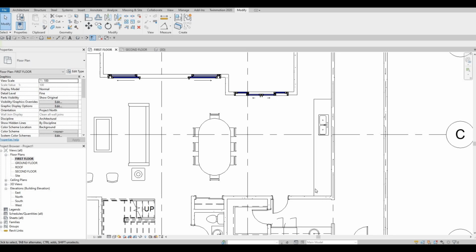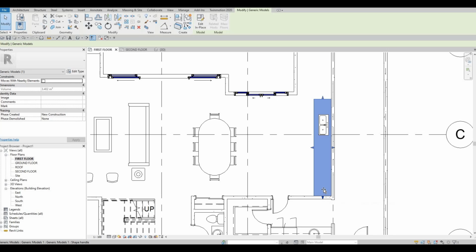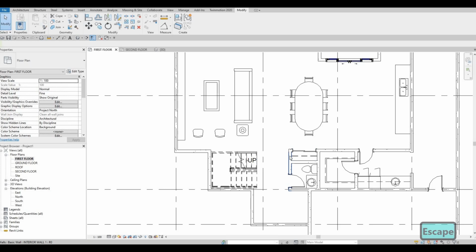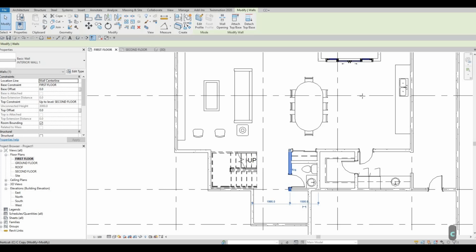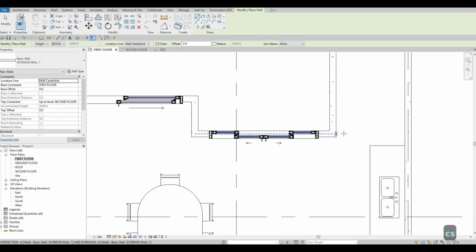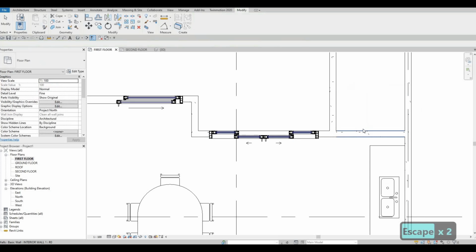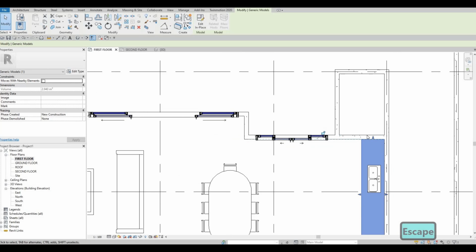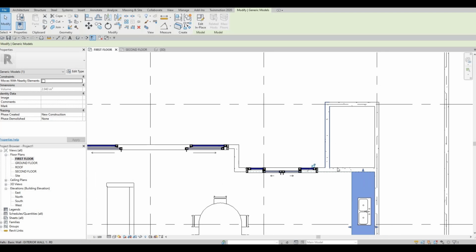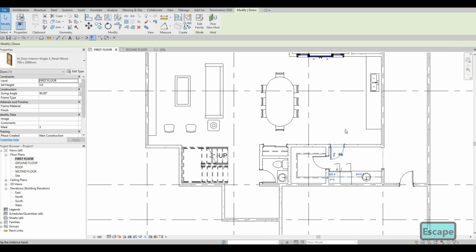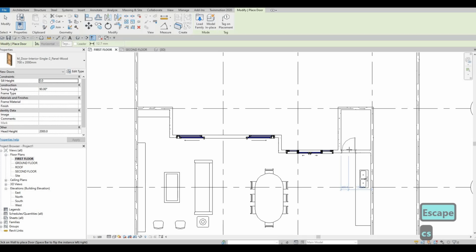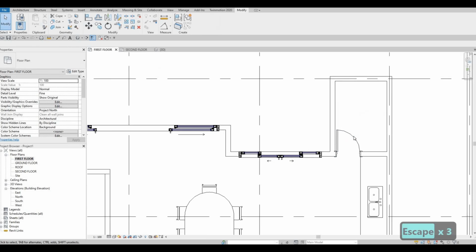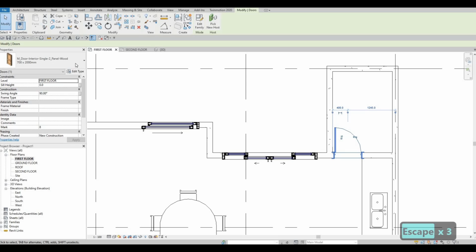So I'm giving it some space now. So spacing. So I'm just gonna pull this one right here, add a wall right there. So that will be interior wall. So I'm gonna select interior, CS, that's create similar, and then I'll put it in the middle right here. So now this is closed off. We can push this back all the way to the wall right there. And then after that, we can add in a door. So I'm going to select this one, CS as well, and then space bar to change orientation. And we could just add this one right there, but we could make this one